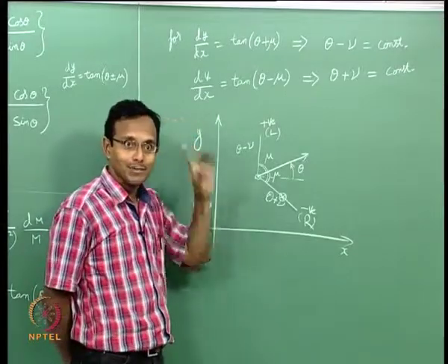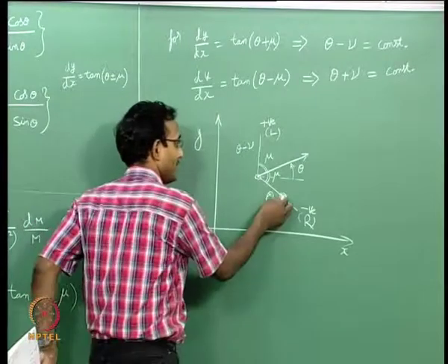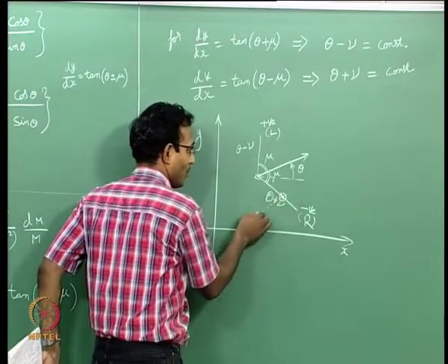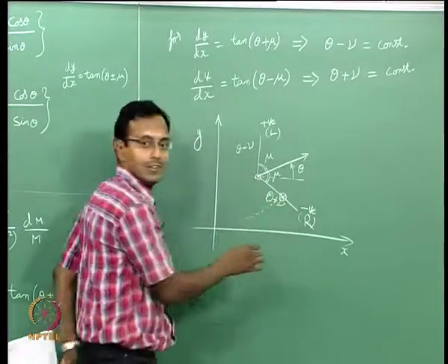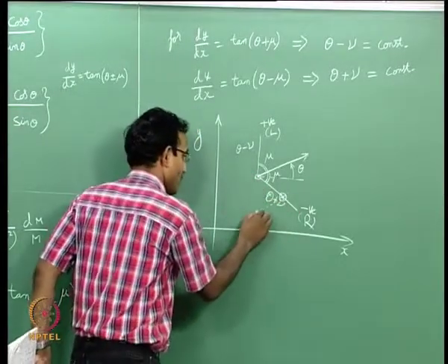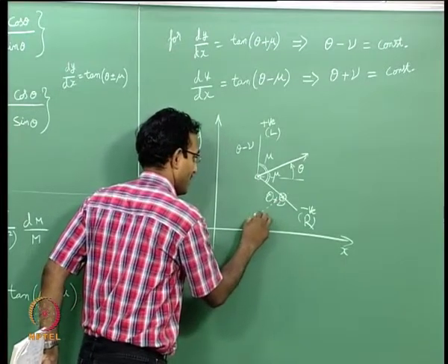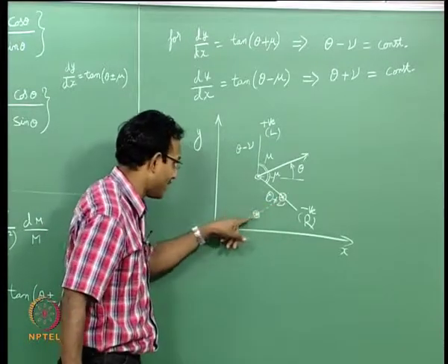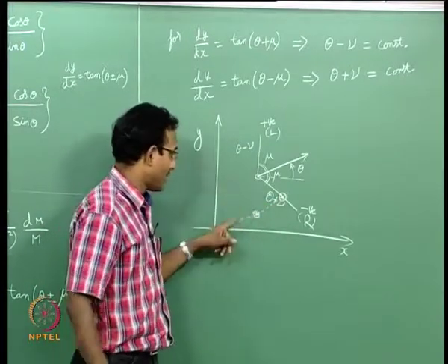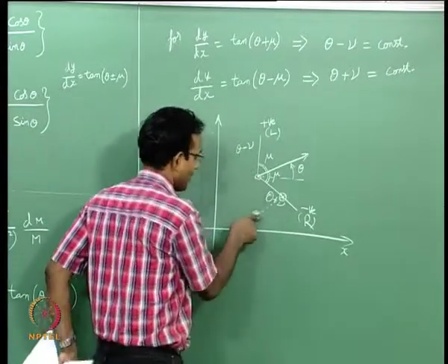Now we go back and think about the zone of dependence, right. This point depends on the upstream cone this direction, right, these two lines. So I am going to say I need one more point given on this, maybe I will use a star here, one more point given on this line of dependence, where this is going to tell me another theta, this is what characteristic?